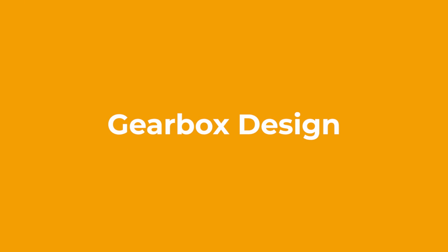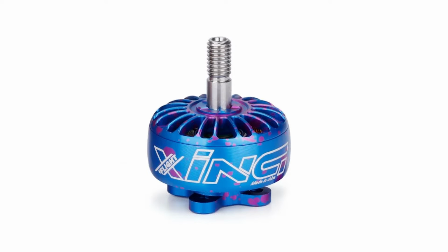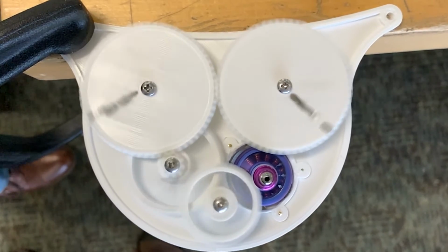As you may have noticed in that concept, the ornithopter needs to have a motor to drive the wings. We decided to use a brushless motor for its large torque-to-weight ratio, but needed to gear it down to obtain our desired speed. To do so, we used a gear ratio of 1 to 94.5.